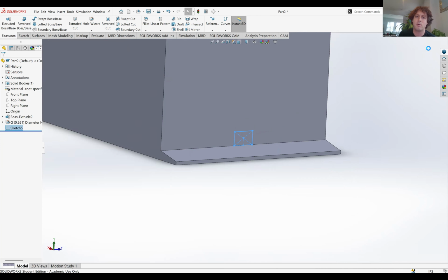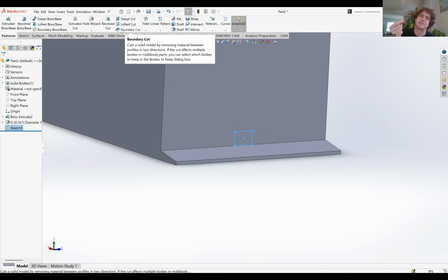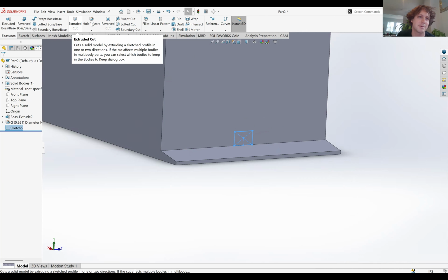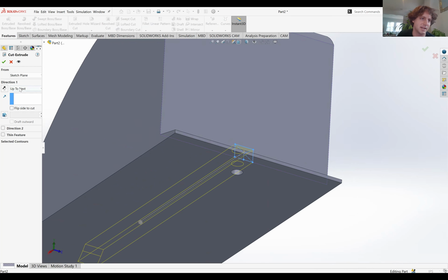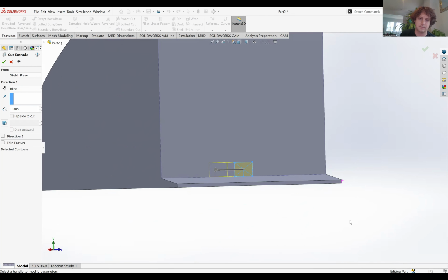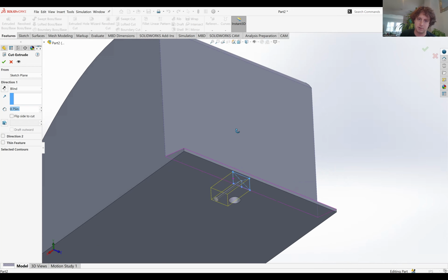Okay. So now we just need this to go slightly past the hole that we made, at least the nut's diameter past the hole. So I'm just going to go extrude cut, and we're going to do this. Oh, no, don't need up to next. We're going to do blind, and where does 1 inch, not two, where does 1 inch get us? Yeah, so again, not really even measuring this, but oh, enter. Okay, and I would say that comfortably gets us there. So that's fine. Actually, we'll make it a little bit smaller, 0.75. That should definitely still do it for us.